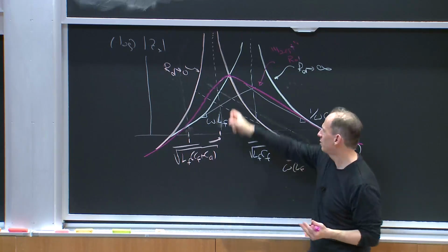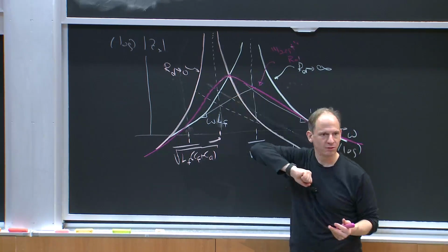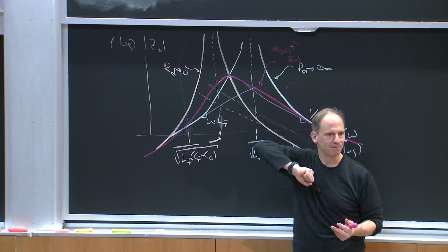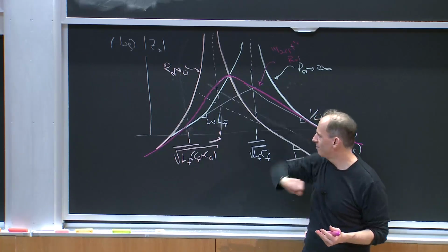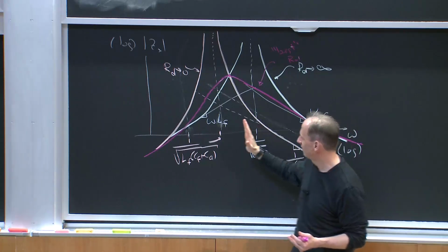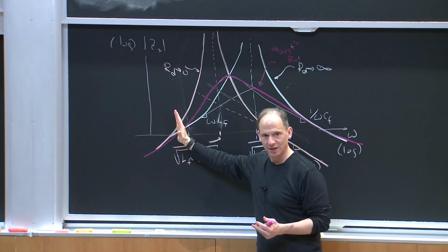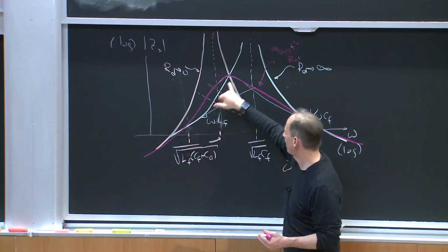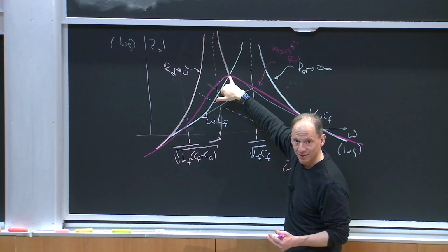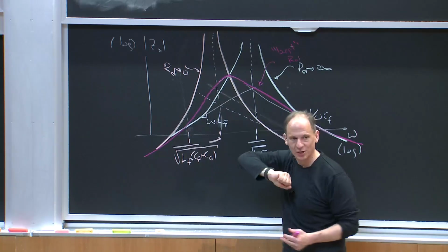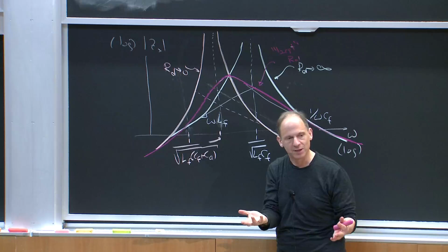So, what do I do if I don't like that value of output resistance that I get? If I make CD bigger, I can slide this down, and then I'll pick a different value, which will bring this intersection point down, and we'll get better damping.